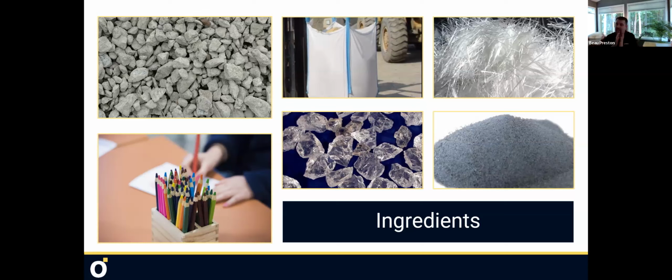So it's got a crushed limestone aggregate core with 2 layers of fiberglass mat running the whole length, chopped fiberglass integrally, natural pigments, and electron beam cured acrylic coatings for the color, inkjet printed images, and then real aggregate facers for one of their other options. So you see they have lots of different facer options. Again, very natural material,